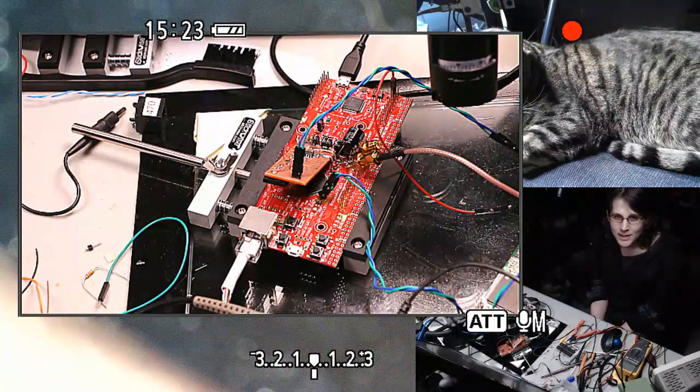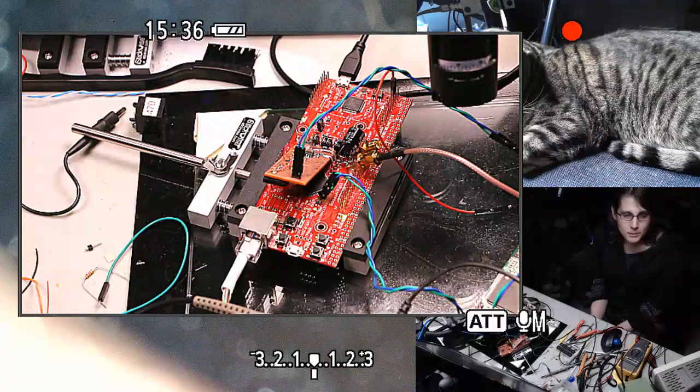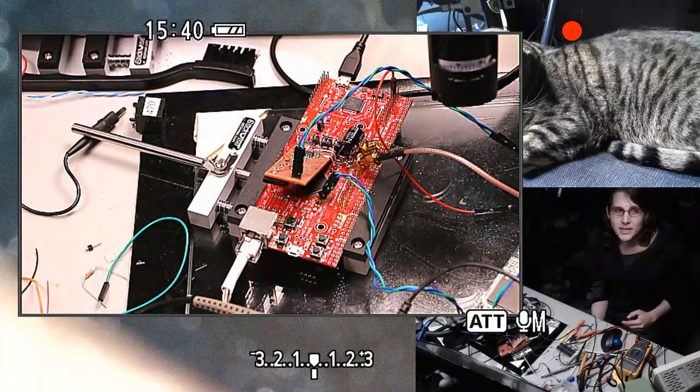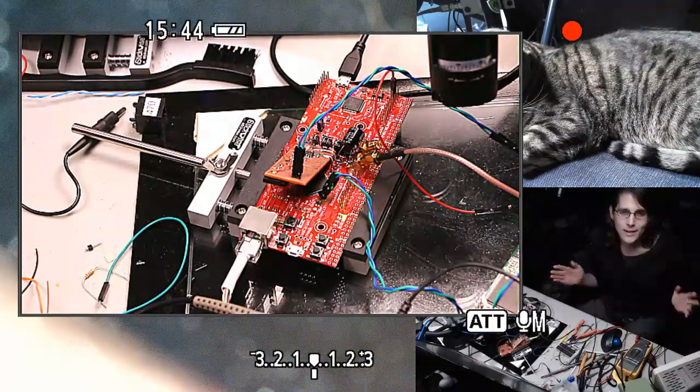So it's possible that a future video might involve doing a simple firmware for this board that acts as an Ethernet bridge back to SPI, and then writing a little program that runs on a Raspberry Pi that acts as a bridge to that SPI device. We could also use UART, but then we have to worry about the baud rate changing anytime we change the clock rate, whereas with SPI we can have a range of clocks that work.